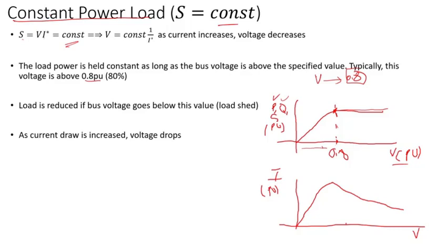Otherwise, if you imagine you have a model that has like 100,000 buses, and you put 0.9, for instance, and somehow there is a bus that has a very low voltage, it's going to diverge. It's not going to converge. So one bus will prevent the entire model from solving. We don't want that. At least having a solution is better than not. If it tells you at this bus, I had to drop load, shed load basically, in order to solve, it's better than not solving at all and having no idea why. So it will give you a setting where you can set this.